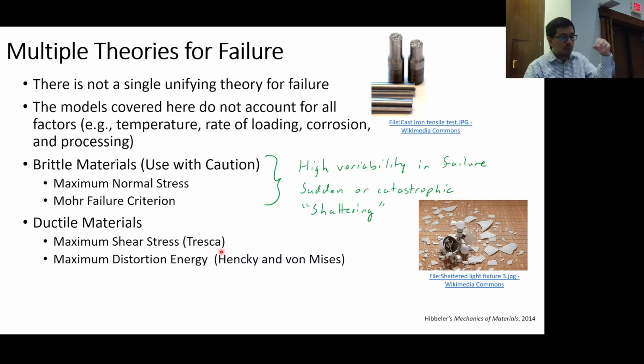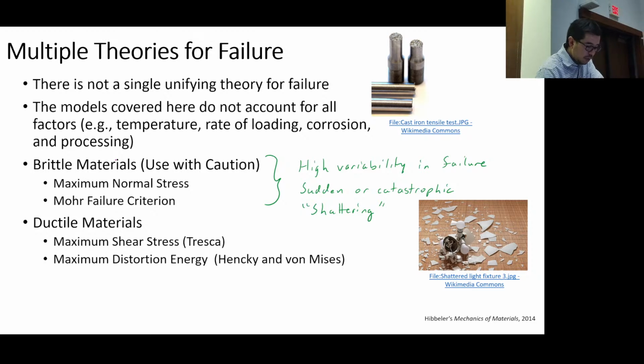So what I'm talking about in uniaxial loading is a material being stretched like this. And so we can say this is sigma 1, and sigma 2 equals sigma 3 equals 0, right? So then, if I draw the Mohr circle, you tell me, what does Mohr's circle look like?